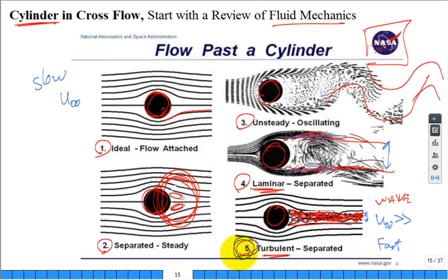Because when you increase the flow, you can get it to become turbulent even in the favorable pressure gradient region before it gets to C. And if the flow is turbulent before it gets to the top, it'll actually be able to navigate and stay conforming to the boundary easier than a laminar flow.